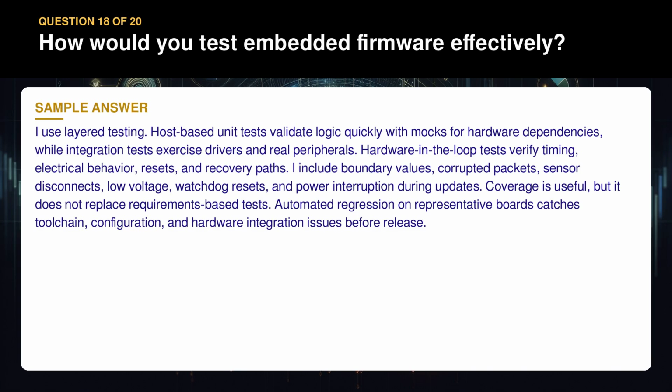Question 18. How would you test embedded firmware effectively? I use layered testing. Host-based unit tests validate logic quickly with mocks for hardware dependencies, while integration tests exercise drivers and real peripherals. Hardware-in-the-loop tests verify timing, electrical behavior, resets, and recovery paths. I include boundary values, corrupted packets, sensor disconnects, low voltage, watchdog resets, and power interruption during updates.